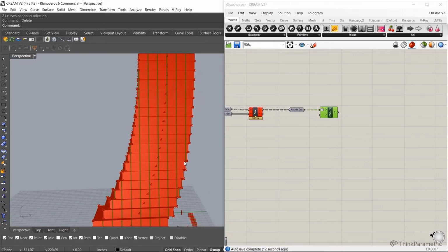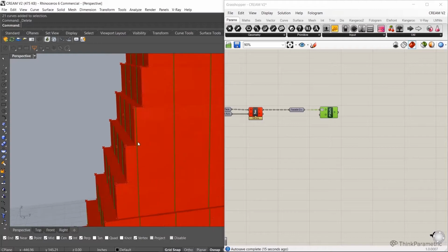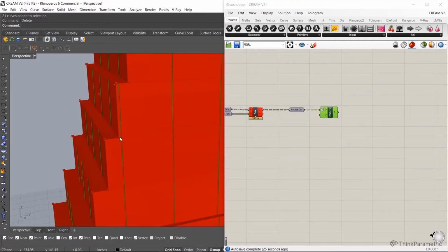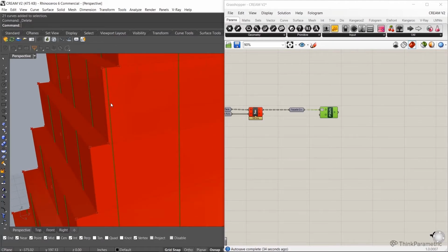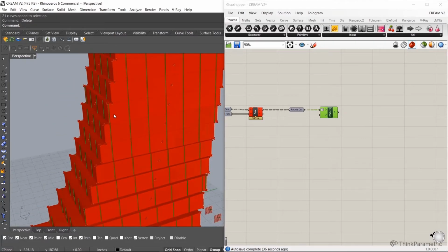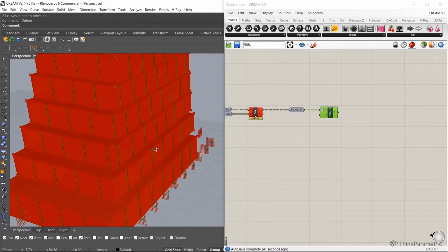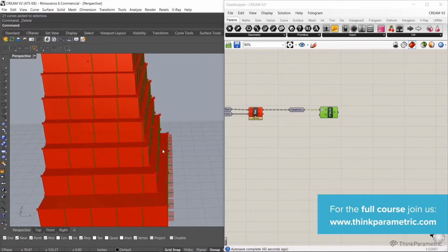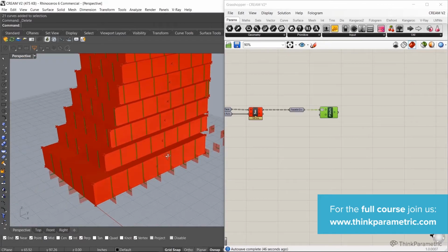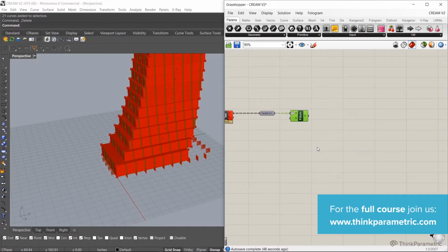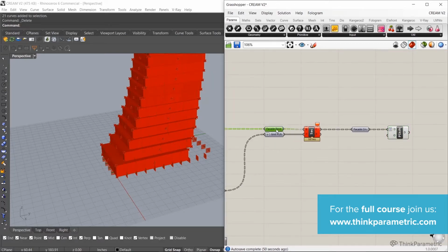And so there's a few things we're just going to add here. You'll see that some of the intersections, like this guy, create a super tiny panel, right? So that is going to later on cause issues. We're never going to be able to create any kind of Revit panel in this little gap that's not a simple rectangle. And simply this is not buildable. So we need to create a little snippet to get rid of some of these strange panels. This guy, maybe this guy if it's too small.